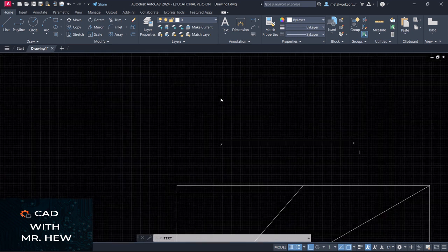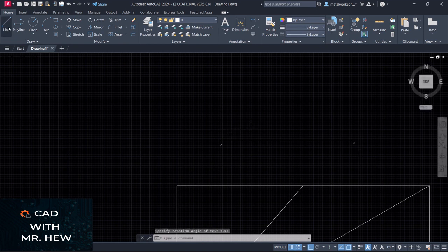So let me draw the line for you now. So we go line, escape, line from the midpoint, right? Now I need to turn off ortho. Ortho will give us only a horizontal line and a vertical line. So look now. I'm going to make the line 210 millimeters. No, I don't need to type at.